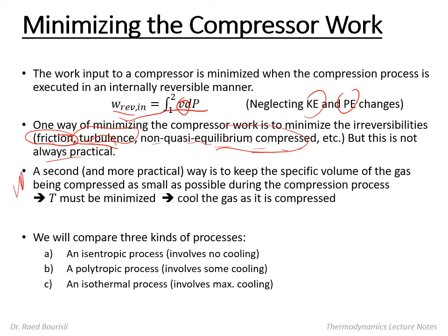A second approach, and more practical, is to keep the specific volume of the gas being compressed as small as possible during the compression process. So keep this as small as possible, and this means temperature must be minimized so that specific volume remains as small as possible. So this means I have to cool the gas as it is being compressed.